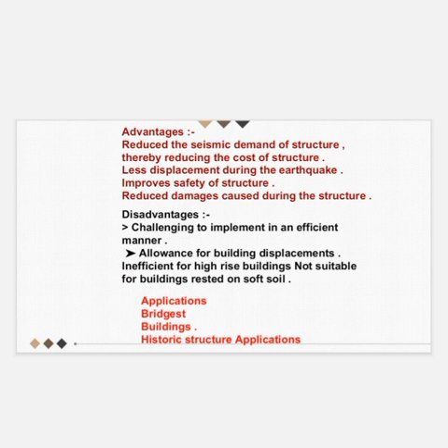The advantages of this system: they reduce the seismic demand on the structure, thereby reducing the cost of the structure. Third is less displacement during the earthquake. Fourth is improved safety of the structure, reducing damage caused during the earthquake. There are also disadvantages of this system. It is challenging to implement in an efficient manner. Allowance for the building displacement is insufficient for high-rise buildings, and it is not suitable for soft soil.